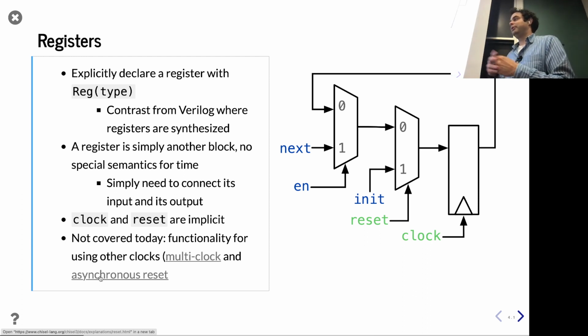The latches, for example, are cool and they make sense on paper, but they're hard to make work at 4 gigahertz at 4 nanometer. So that's kind of why they weren't chosen. But not everybody using Chisel is doing 4 gigahertz at 4 nanometer, right? Maybe we're doing 100 nanometer SkyWater, in which case we should be doing latches or something. So this is one of these things where perhaps you will have a black box library internally for your project, in which case you will be happily instantiating these modules.